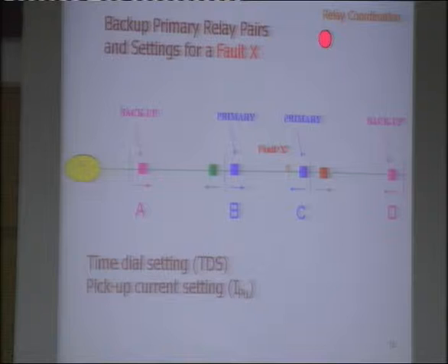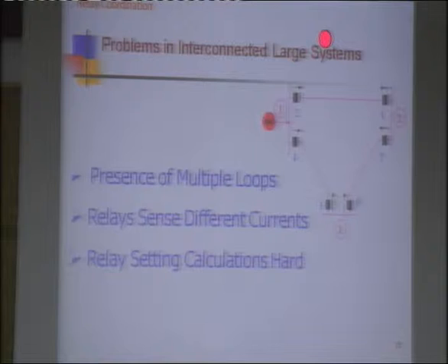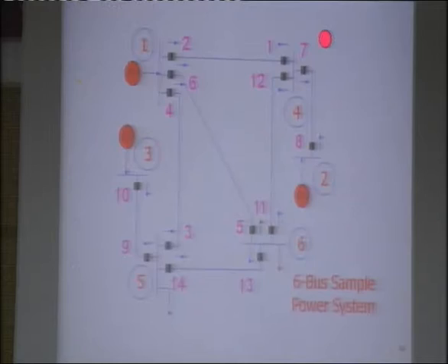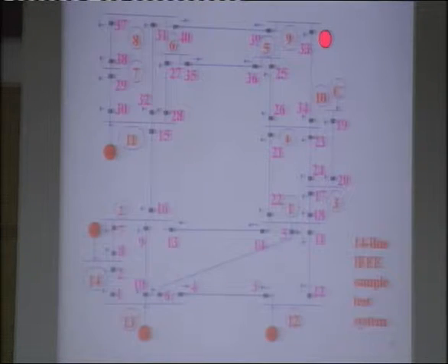Then there was a need of automatic isolation of the transmission line, but the problem with the fuse was that it used to be replaced by another fuse. Then protective relays were introduced which will make the circuit off in such an eventuality of fault, and after some time it will make the connection back on. So this was the development of relays.